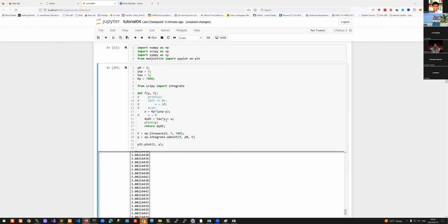And that's because this process is inherently unstable. The process is constantly trying to run away. And in proportional control, we only take action when there is a difference. So the process tries to run away. The moment it goes a bit above the set point, we start applying this flow rate. And by the way, this is an exit flow because this number is going to be negative.